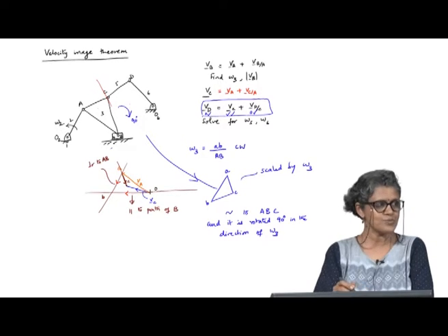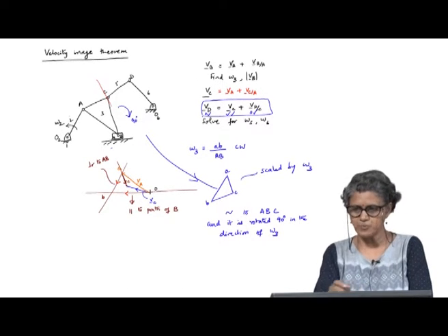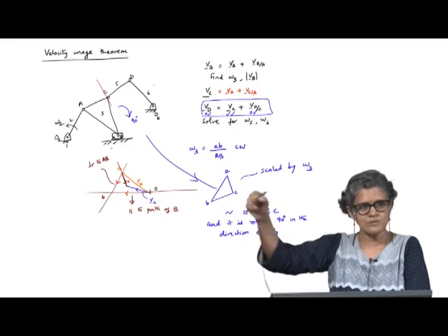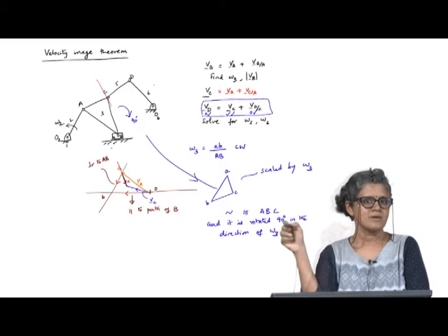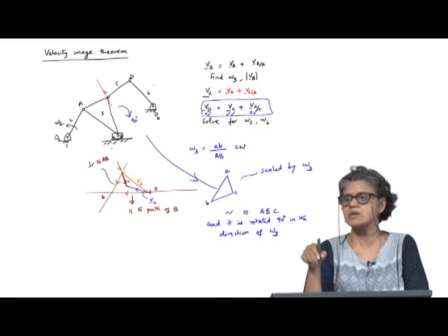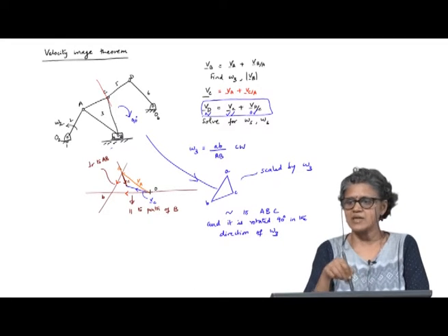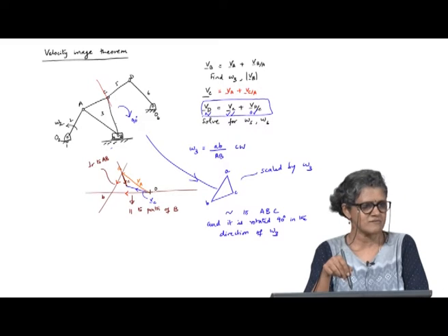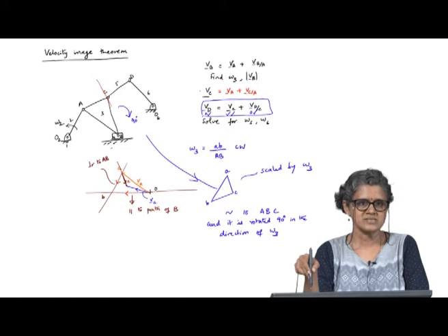I have to go through each of the motion transfer points, so to speak, to connect them and find all the intervening angular velocities before I get to the angular velocity that I am really interested in. Okay. So, I can't skip finding any of the intermediate angular velocities here, okay. But I may just be interested in omega 2 and omega 6, for instance.